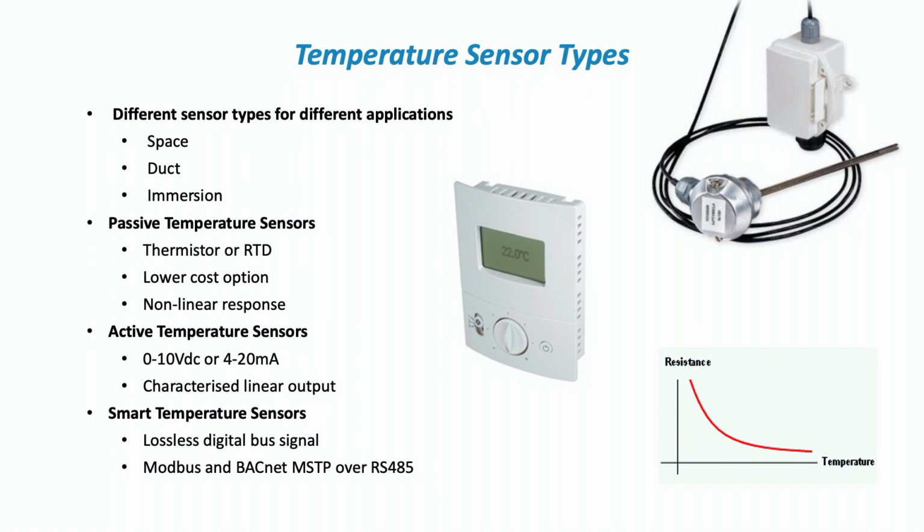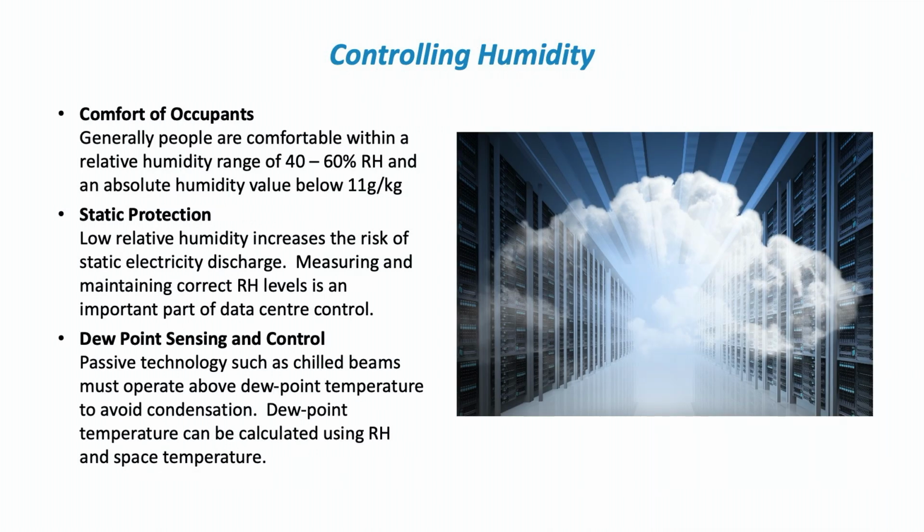Sorry, BACnet MSTP, I don't think I've covered that in here. That's master slave token passing, but that's the version that goes on RS485.